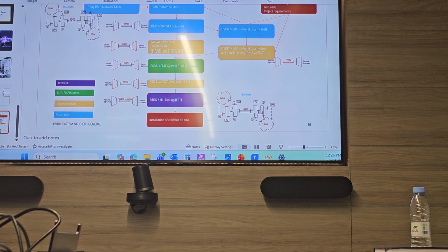Then they will run complete network simulations of faults. You can do it automatically, which will simulate a fault on each busbar. Fault results could be automatically produced.